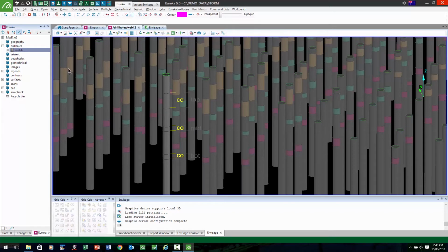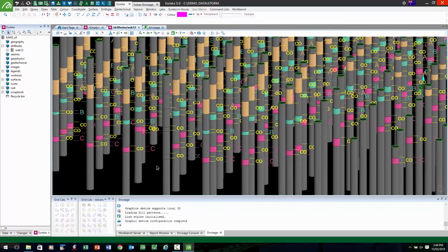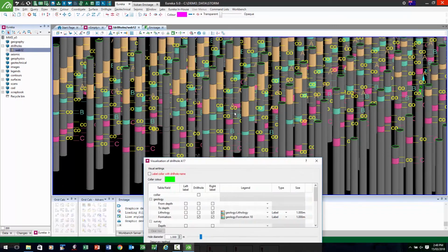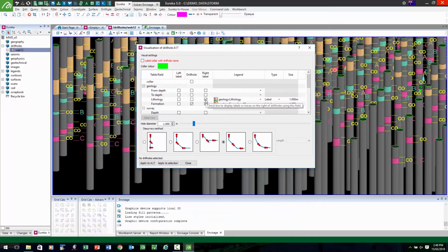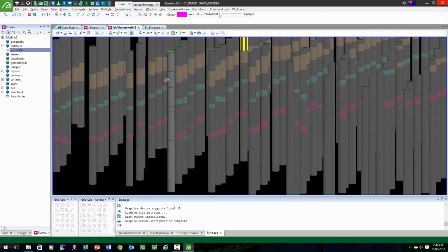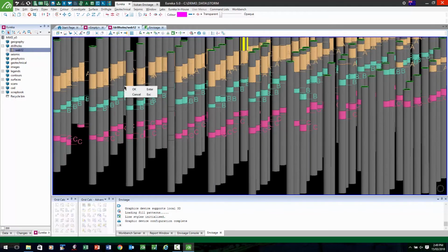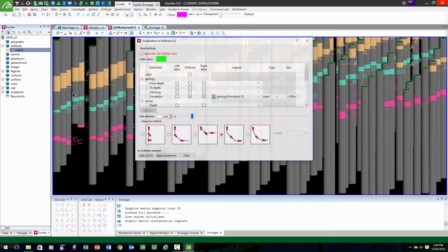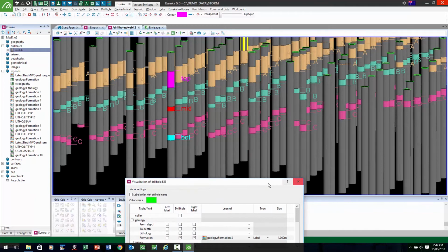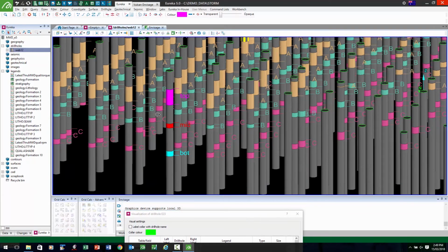And what I'll quickly do is just relabel those holes based on the formation pick. So in this case, it's going to be formation. We'll turn off the geo label and apply that to all the selection. And you can see in here I have top, middle, and bottom. Actually, what I'll also do is I'll color that. So in this case, I'm going to use a pre-existing legend called legend number 3, I believe. And that has got the colors in it for my top, middle, and bottom.